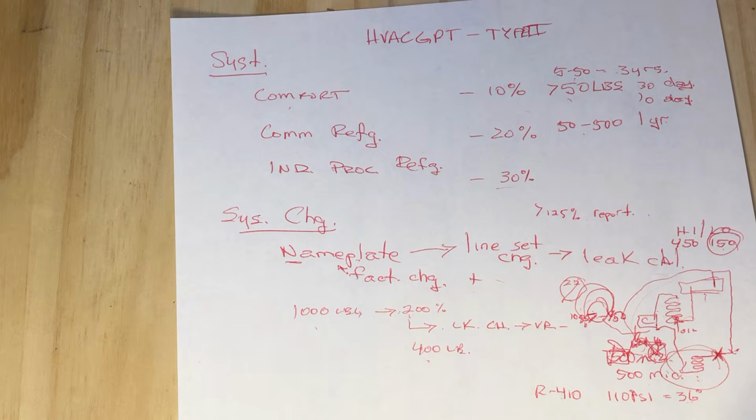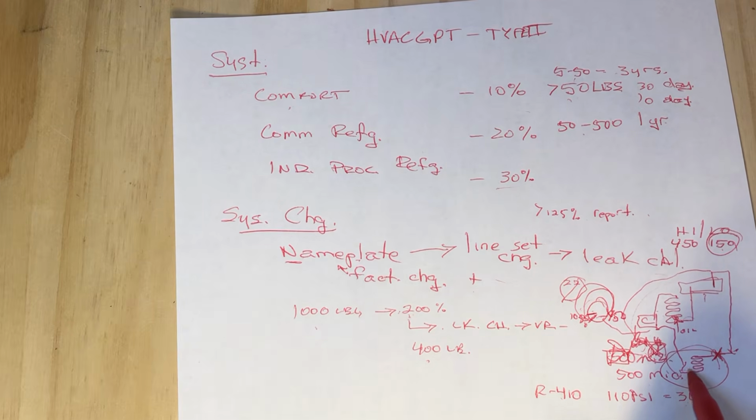So it's not going to be liquid at 110 psi slamming up against the liquid water if this is a water barrel with the liquid refrigerant flowing through it. That could make the water freeze, cause the tubes to freeze and then expand and crack, and we have another problem. So sometimes we put a little bit of vapor pressure in up to the saturation temperature of the refrigerant freezing, so we get it above 32 degrees,